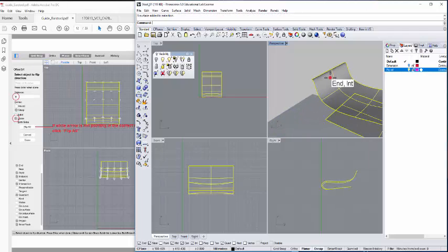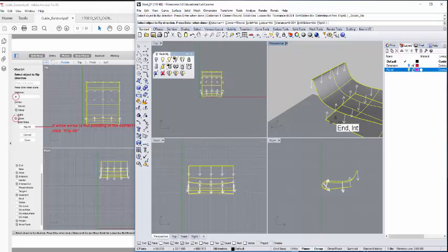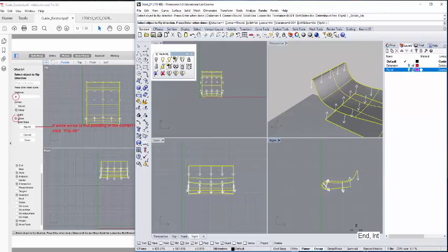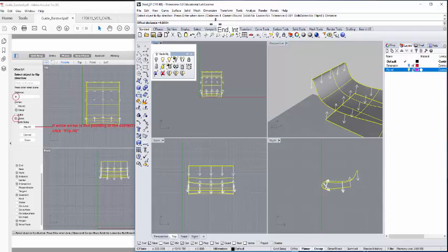Right, let's take the surface. Click surface, offset surface. Okay, take note. My direction, is it correct? Yes, it's correct. I'm just going to show you how it looks when it's flipped. Can you see? Right now it's offsetting outside, but I want to flip inside. Okay, the distance here, right, is 8.